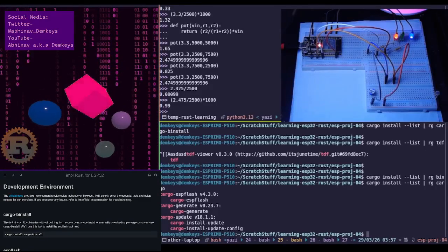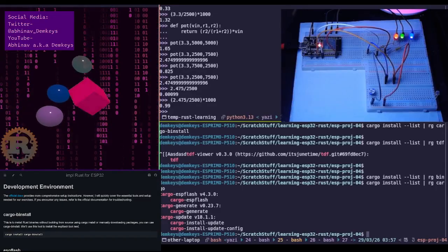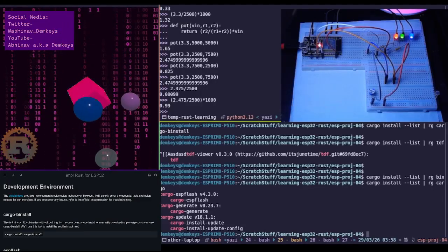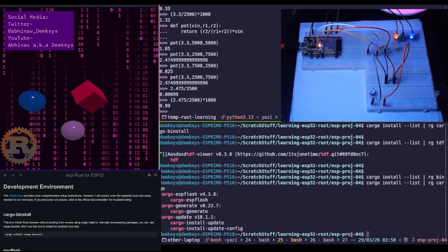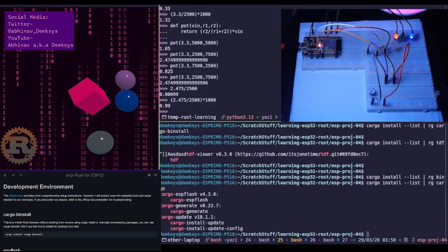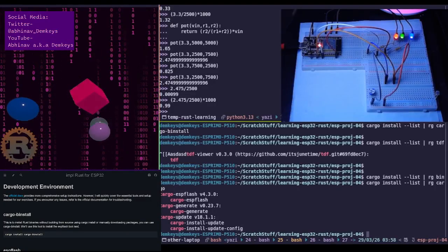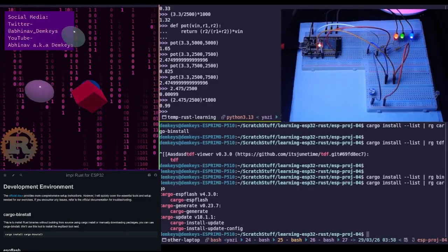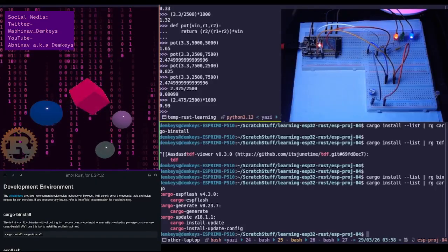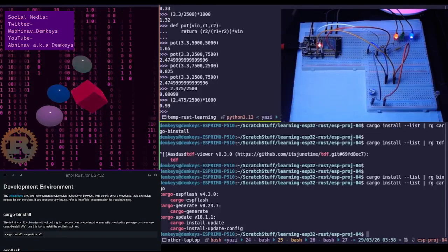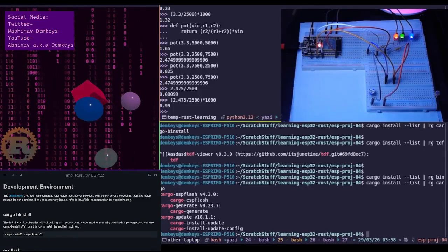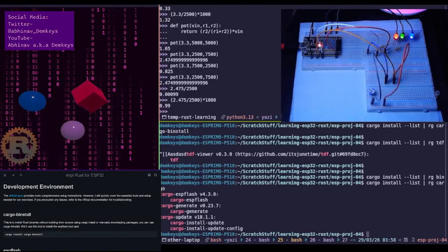Okay, standard optocouplers are almost exclusively designed for low current range, typically handling signal level currents between 10 milliamps and 50 milliamps. Think of them as high-tech messengers rather than quote unquote muscles. They excel at passing information while keeping circuits electrically isolated, but they generally lack the power to drive heavy loads like motors or large heaters directly.